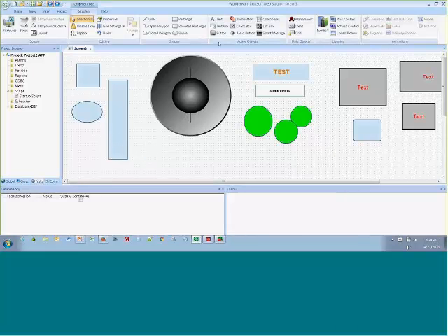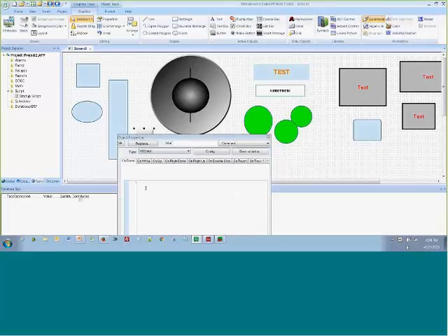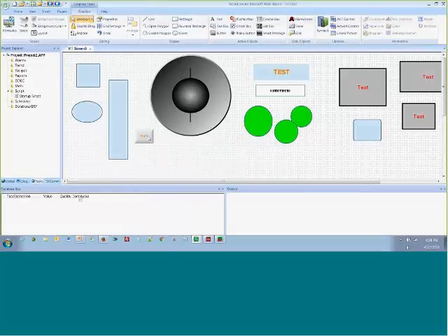Now, what you could do is put a button or a drop-down here on the screen and say, okay, I want this to be PLC1, or maybe it was machine, or conveyor, whatever. And on the command, I could use that same style, or I could say PLC1 equals 127.0.0.1:502:1, and then make a copy of that button.